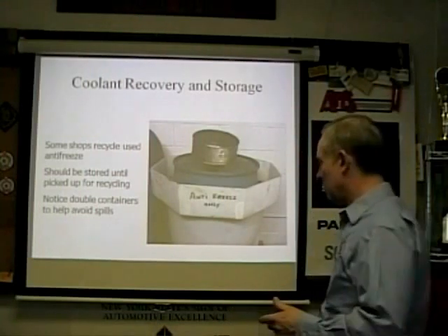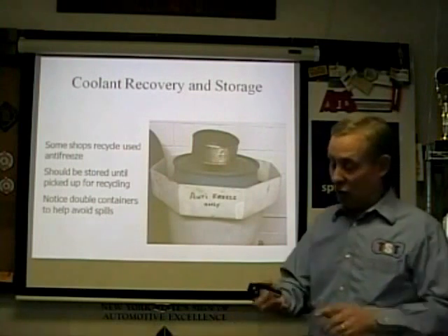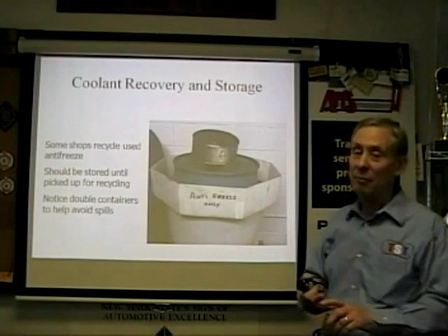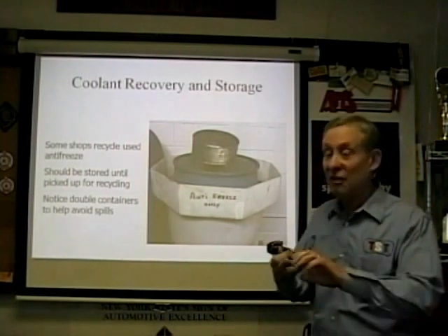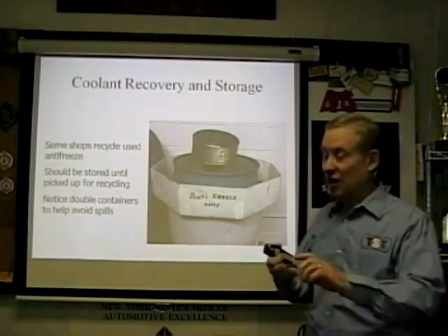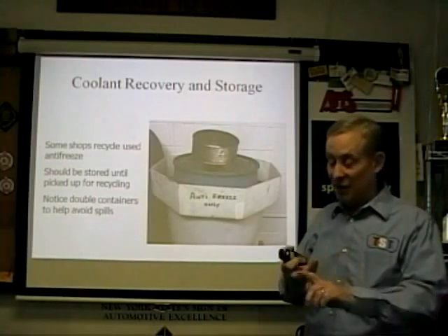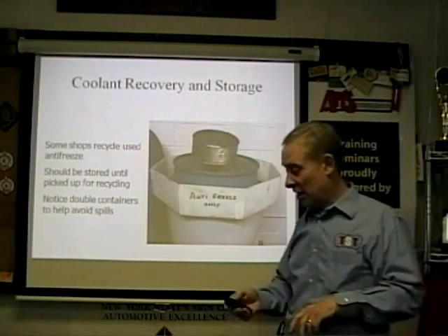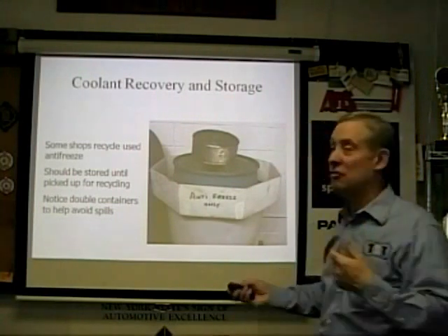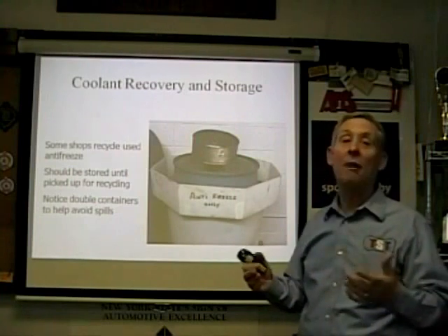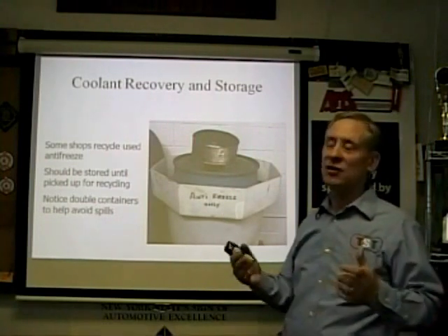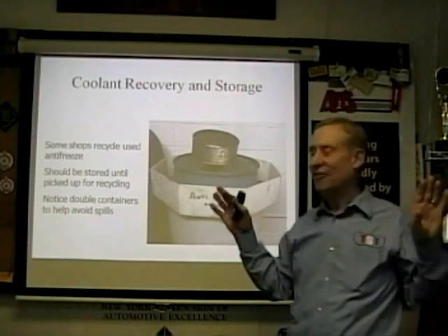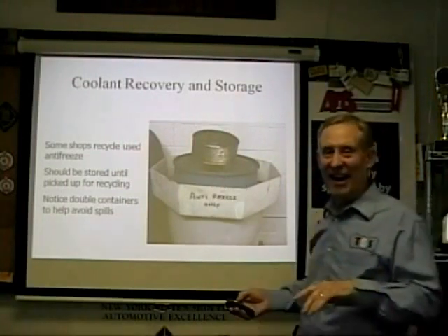And also, don't flush this down any sewers or anything. Don't flush it down storm drains. Notice the double container. Make sure it's pumped out by a certified provider of this service. That leaves you a manifest, because you are liable for these things cradle to grave. That's right. And it's actually better, in my opinion, to use a company that has their own remanufacturing facility, because as soon as they've remanufactured it, that's the grave. You're not liable anymore. That's right.